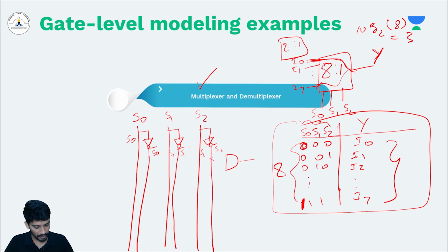You need to connect all zeros to this first AND gate because you want the all-zeros combination to appear here. Let's take it as P0, because it is a partial output but not the complete output. So P0 will be S0 bar dot S1 bar dot S2 bar.